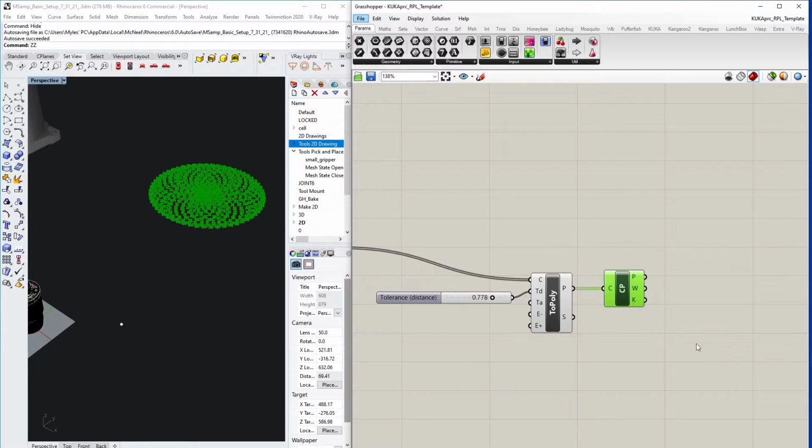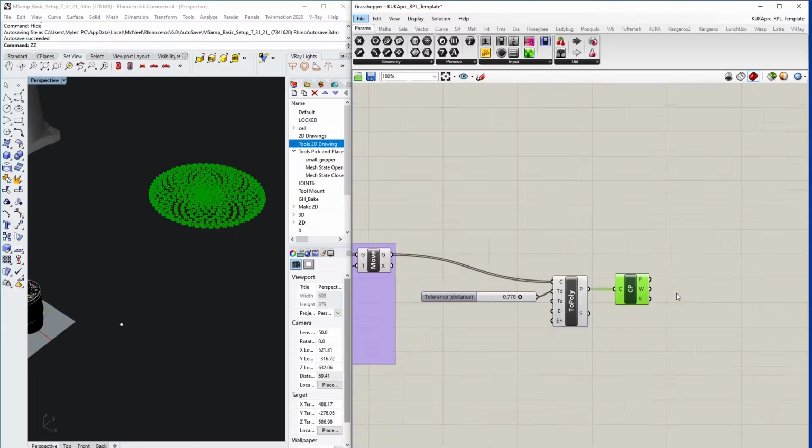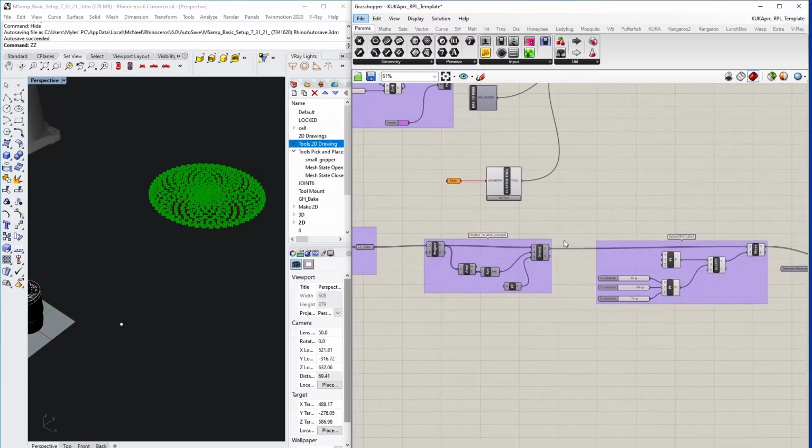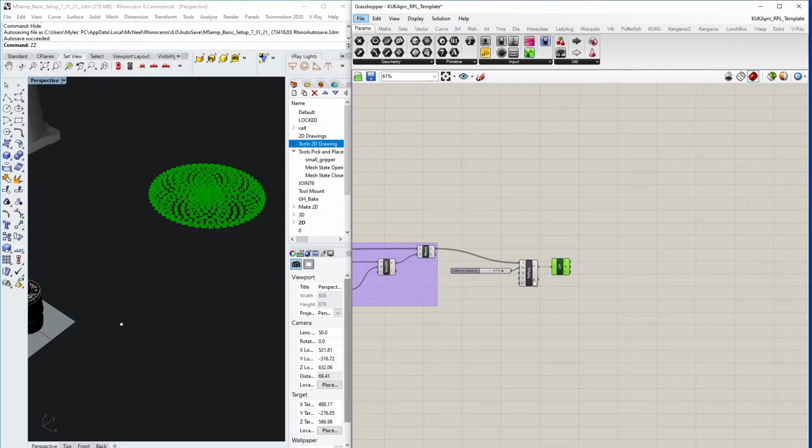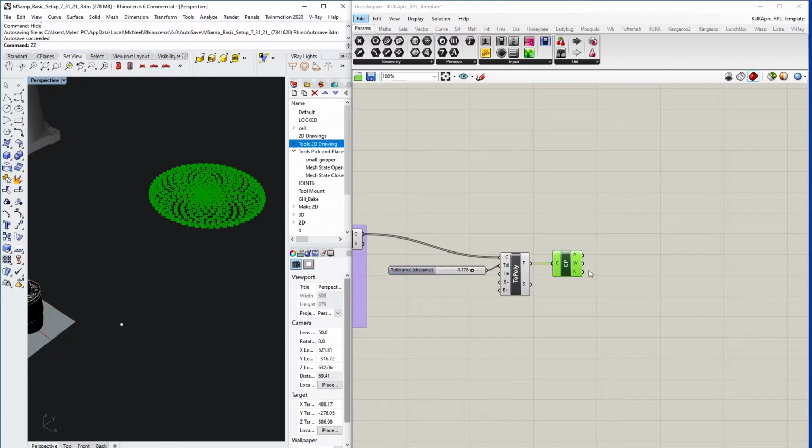For now, we can leave our tool as is. So if we go to our custom tool, we can take off 90-degree rotation, which we know is not needed at the moment, and leave it straight up at a positive 138 millimeters in the Z direction, and manipulate our planes so our tool and our planes line up.